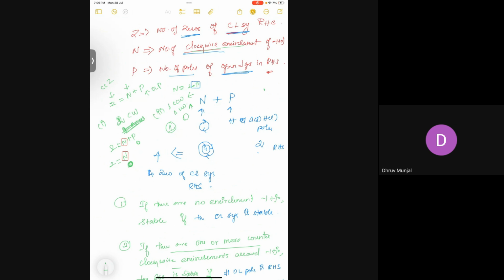I'm not saying it is in the right of the plane. Only if it is in the right of the plane do you have to worry about it. This is the open loop system's poles and zeros. Even if the open loop poles and zeros are in the right of the S-plane, the closed loop system's poles and zeros can be in the left half of the S-plane, based on the gain tuning, parameters, and the location of poles and zeros.